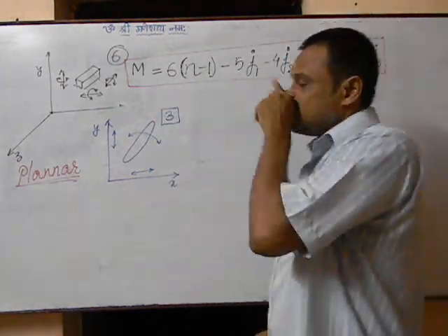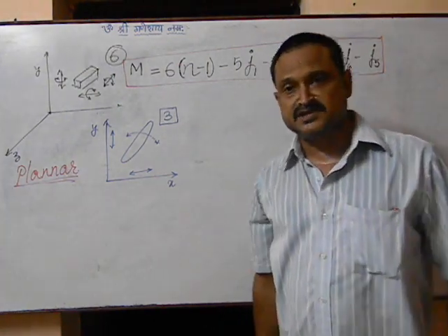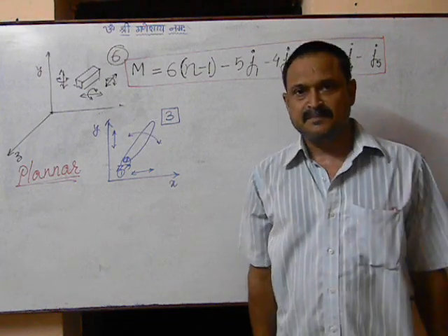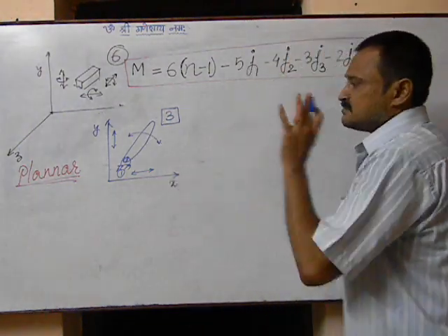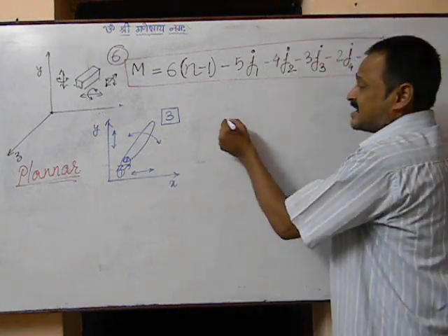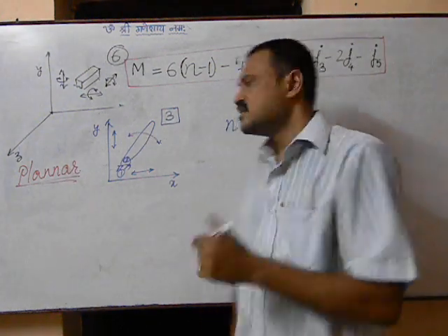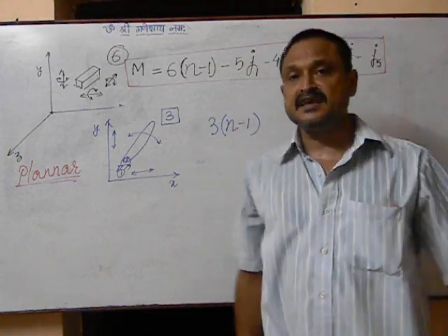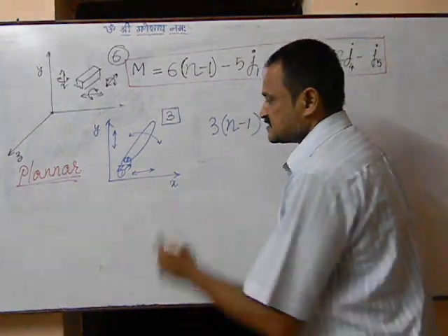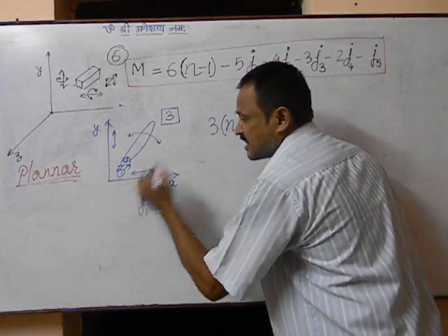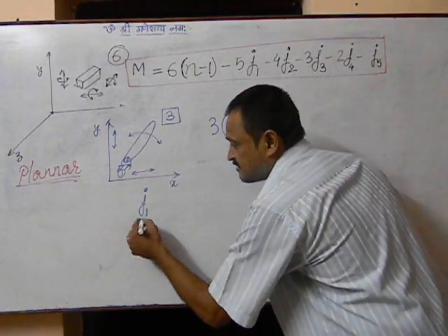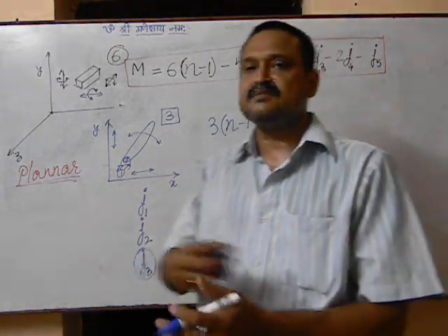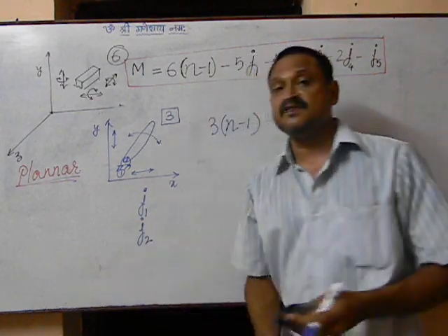Right? Now again we'll move with the same concept. If it is a mechanism, then a number of links will be involved, out of which one link will definitely be fixed, which can be called the frame. Fine. So let us say in my given planar mechanism there are n number of links, out of which one is the frame. So n minus 1 links can move in the plane, and they can have a maximum of 3 degrees of freedom. Right? Now in a planar mechanism there can be joints having 1 degree of freedom, there can be joints having 2 degrees of freedom, and if I say joints with 3 degrees of freedom, that means it is detached. So there is no chance of having a joint with 3 degrees of freedom.